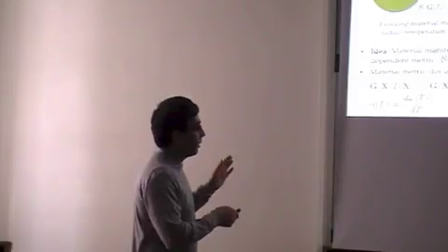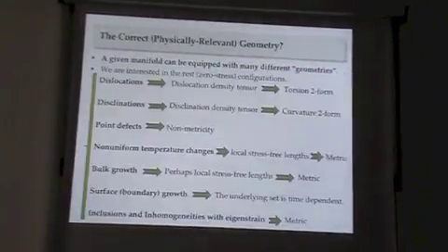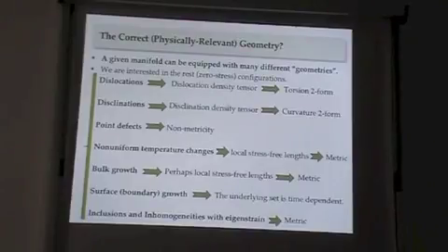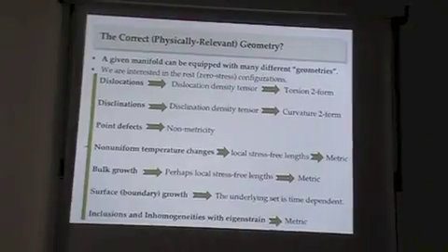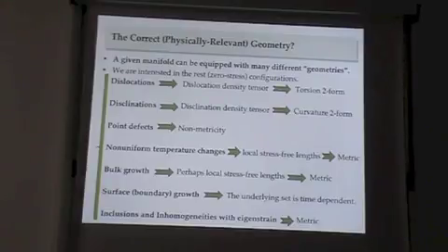In the case of thermal isotropic materials, you could explicitly write that and do some calculations, but just to give you an example. And before I move on to inclusions, let me also mention this. What is this material manifold where you're stress-free? It's very problem dependent. Given a set, you could give it many different geometries, and you could write very long papers that don't mean anything, so you have to really understand the physics.